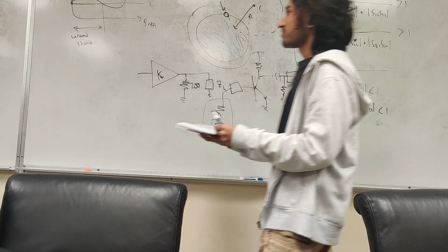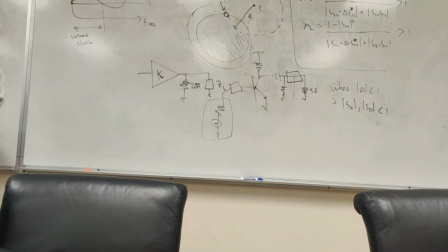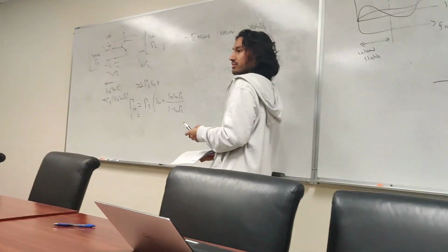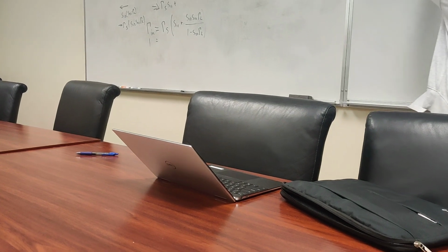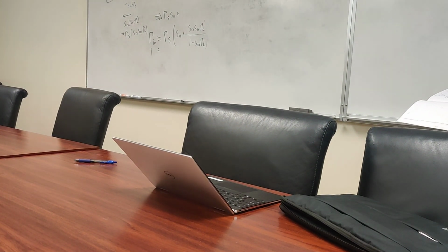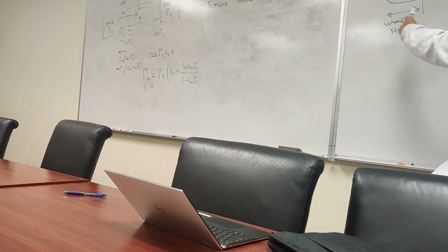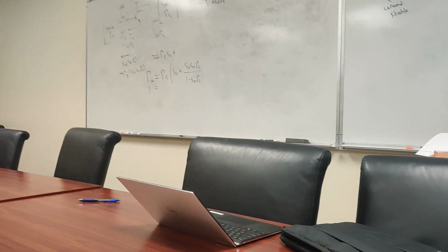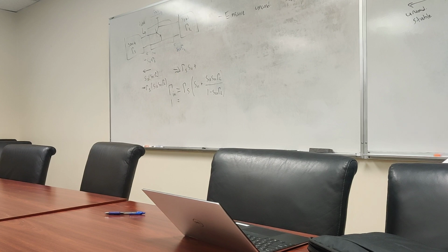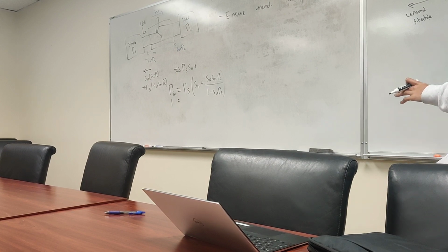Okay. So your S parameters change. And what you typically want to do is if your system is close to, if it's going to be like this, right, you want to insert loss. Whatever this oscillation is, if that's happening, that could potentially happen because you have too much reflection back. To do so, to degenerate a signal, you make it lossy, you put loss in the path.